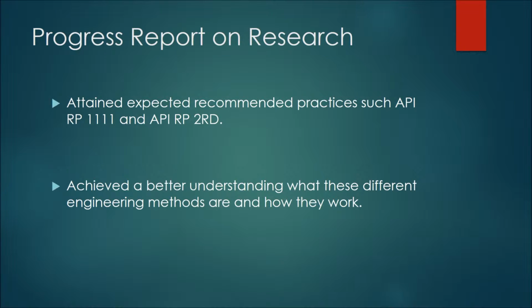Hey guys, William Fernandez here, and I'm going to be talking about what progress we have made so far concerning the engineering standards that we have researched. So far we have attained API RP 1111 and 2RD and are reading through the practices. We have decided it would be most appropriate to do a comparison between the Barlow equation side by side with API RP 1111 and 2RD.